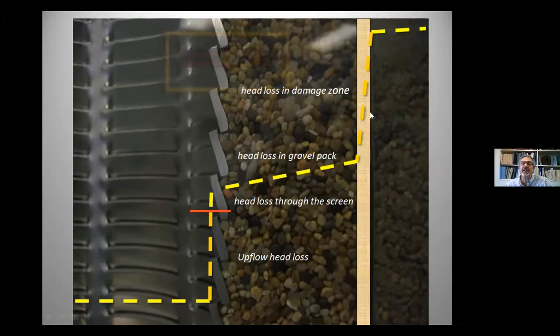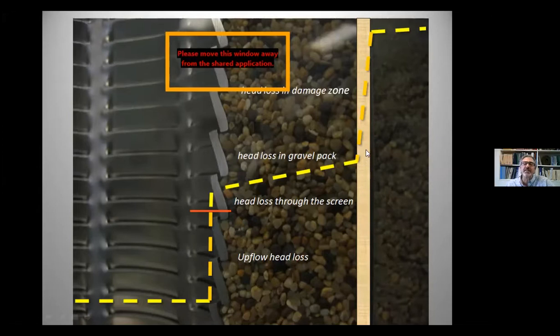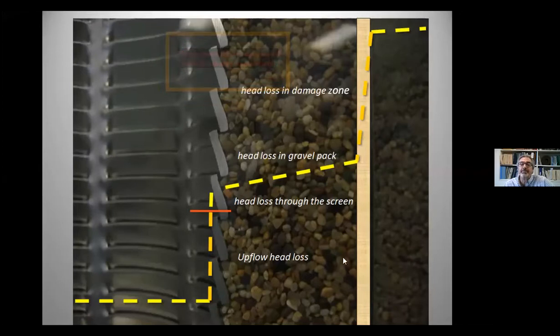This damage zone, again, would be residual drilling fluid, or inadequate development of the zone that left this fine grain matrix, this bentonite material or hole stabilizers that we used during the drilling process. Those were fine as long as you were trying to maintain the hole stability during drilling. But now that the well's been gravel packed and the screen has been installed, this becomes an impediment to letting the water come through in a laminar fashion through the gravel pack and into our screen.